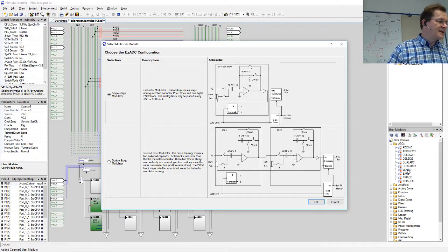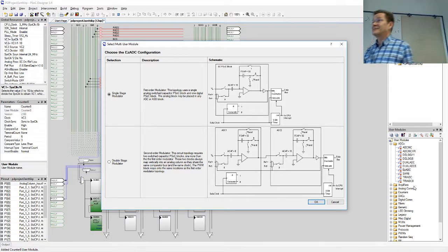All right, and it looks like it has either first or second order modulator. So this practically looks like delta sigma topology. Well, who cares? As long as we get bits. If you have an A to D converter, you can always go and afterwards do the calibration, and with the PSoC circuit, the calibration can be done by software because of the band gap.